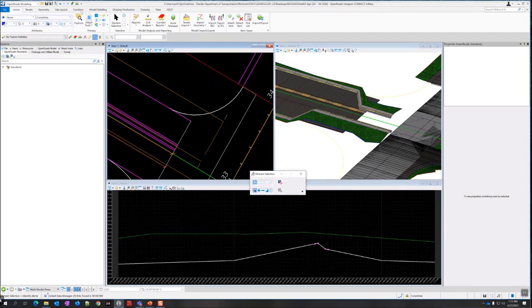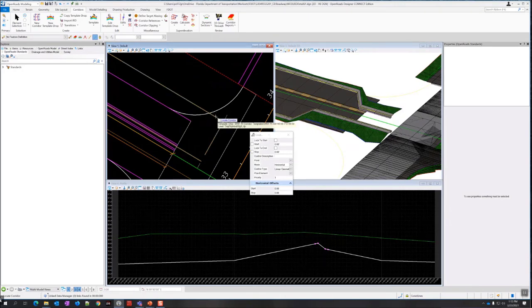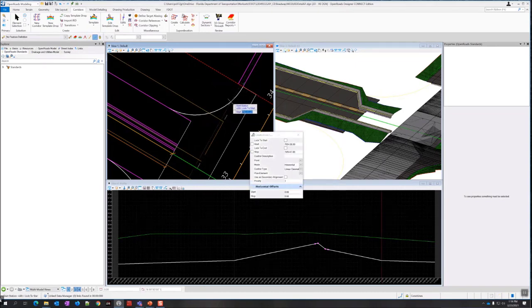So now I come over to the corridors tab. Just go to the edits drop down where we were before, but make sure you click the drop down because you're using a different command now. We're using create point control, the last one on the list. And the corridor we're going to select first is the SR61R. So select that corridor handle. And the start station, we can just lock it to the start, or you can snap it right here, but this is the same place that we started it. So I'm just going to click Alt to lock to start, or just check this box.